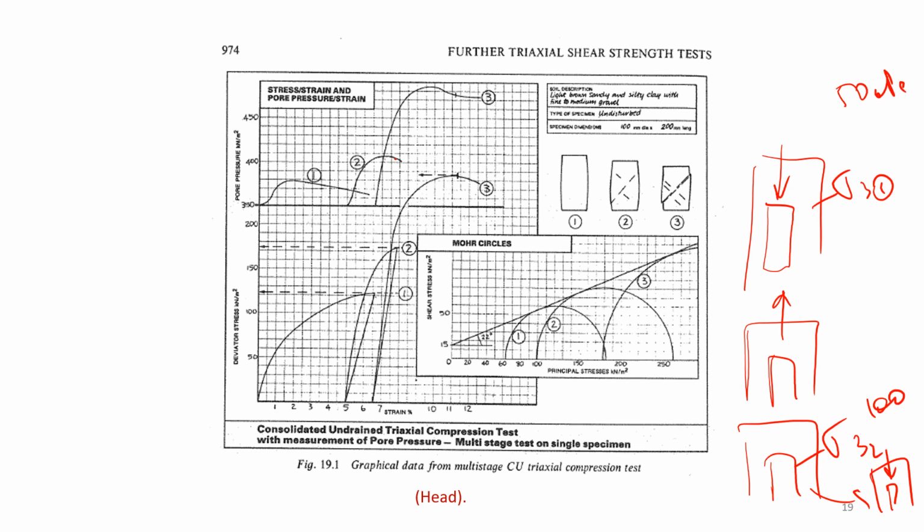You have to pick these values. Generally for the third, when you have sigma 3, 3, let's say 200 kilopascal, for example, you can already shear to the end. You don't worry about maximum strain, it could be up to 15%.